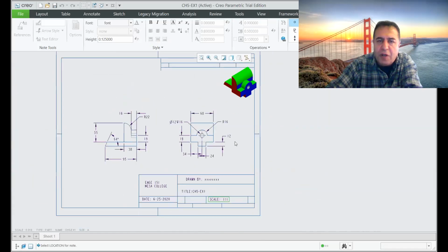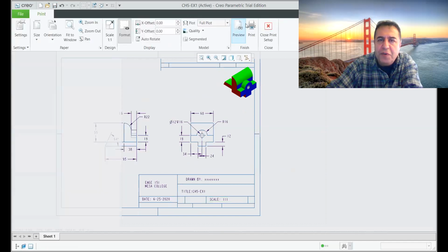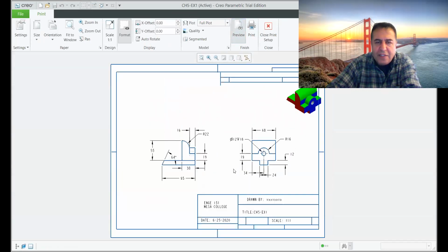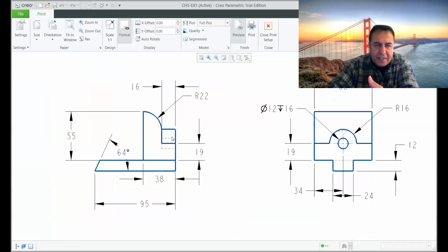This part, solid model. Now, if you want to look at the blueprints, you say File, Print Preview. You can see that now, this is your blueprint. See that? It looks blue, right? So that's a nice dimensioning. Center line, hidden line. This is the hidden line for this hole. That's a hidden line. So that's a standard US system of drafting mechanical drawing.